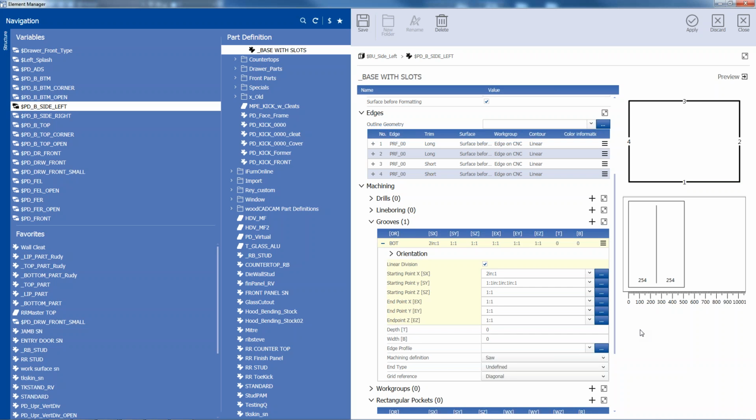We have 5 spaces. 1, 2. We only need 4 spaces. So if we go from the center, the bottom will be 1 inch to the bottom slot, 1 inch, then to the upper slot 1 inch, and then from the bottom slot to the floor, or to the bottom of the toe kick. Yeah, I get it. We have one too many 1 inch in there. Get rid of one of the 1 inches. There's only 3 slots. We got 4 there.